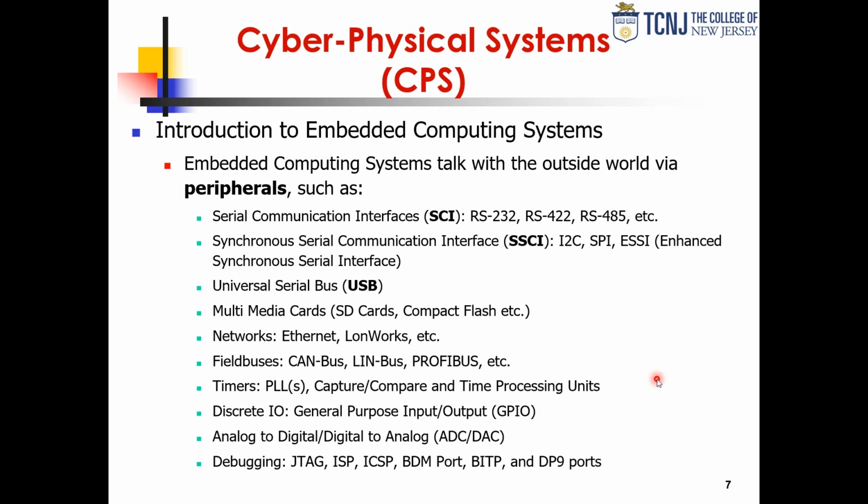So serial communication interfaces. Your basic 2-wire, 2 to 5-wire UART, whether you're doing hardware flow control or not. That's an asynchronous communication interface. What we call the second layer, the link layer of the protocol, looks pretty much the same as a UART, but at the physical layer, there are variations that are more robust, electrically resilient, and you have all these different standards, RS-232, 422, 485, and so on, whether you're just connecting something simple or have some type of bus in an industrial environment.